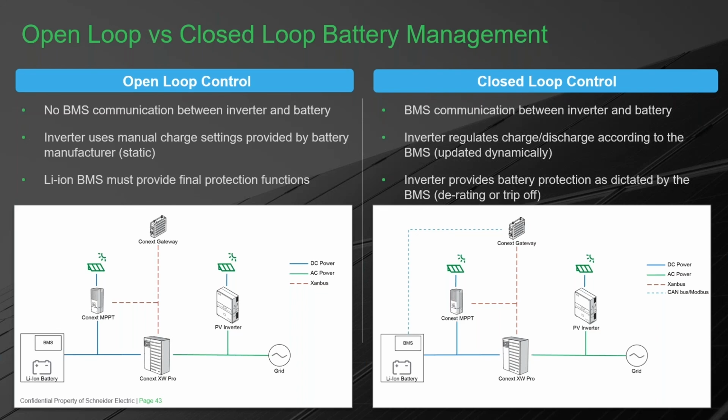The manufacturer designed them to behave very similarly, so there's no need to have any type of control. They plug in electrically to the DC bus and there's no communication. Here, in this architecture, the battery manufacturer provides an instructional manual with settings, and during commissioning, the installer manually enters the settings into our system.